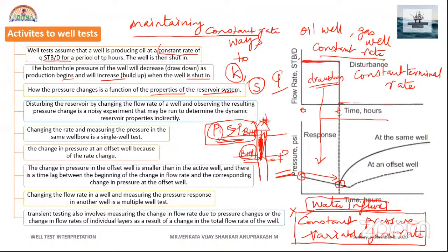Because of that, you'll see some changes in the well, and that is called wellbore storage. That is why we don't see the wellbore storage factor in the drawdown test. And what is this test? This is under the shut-in condition, where we are measuring, and this is called the build-up test.